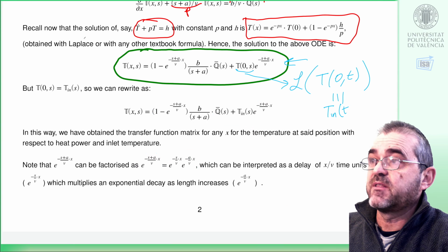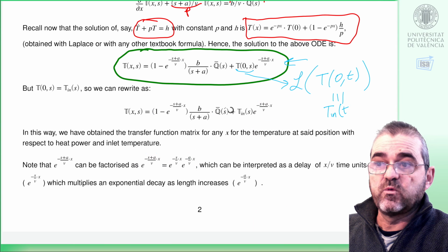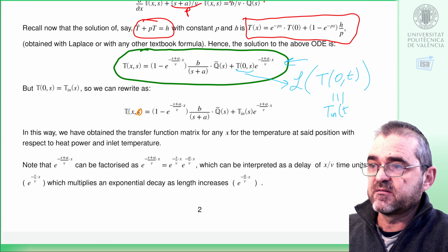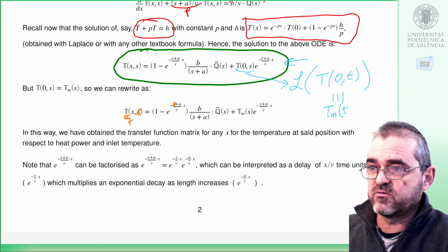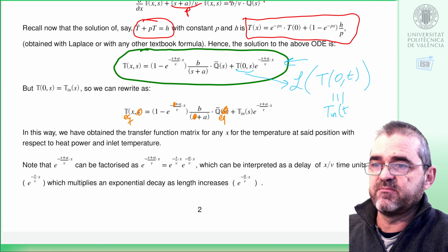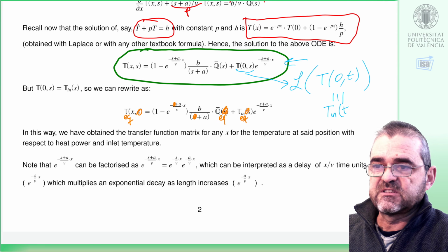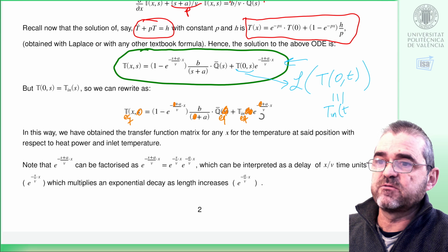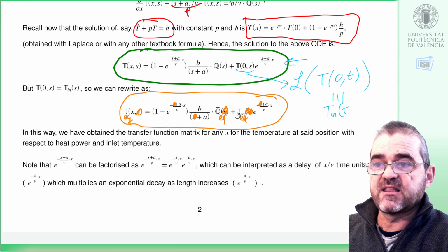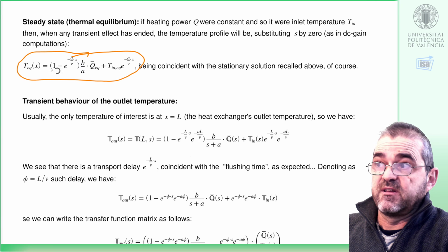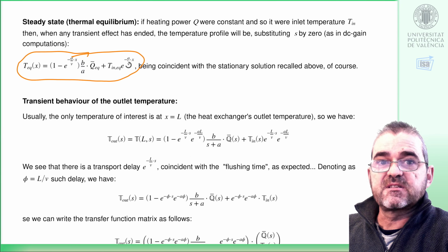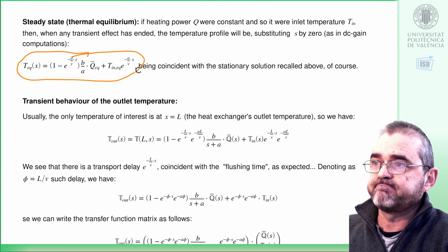It's important to see that if we want to get steady state, once we are in transfer function, Laplace domain, we need to set s to 0, so we get equilibrium temperature equal to transfer function gain, which is setting s to 0, times the equilibrium input. So if I put some constant equilibrium values and I set the Laplace variable to 0, then I get this steady state solution, which is this expression that coincides, of course, with the steady state solutions of the standard heat exchanger formulas.